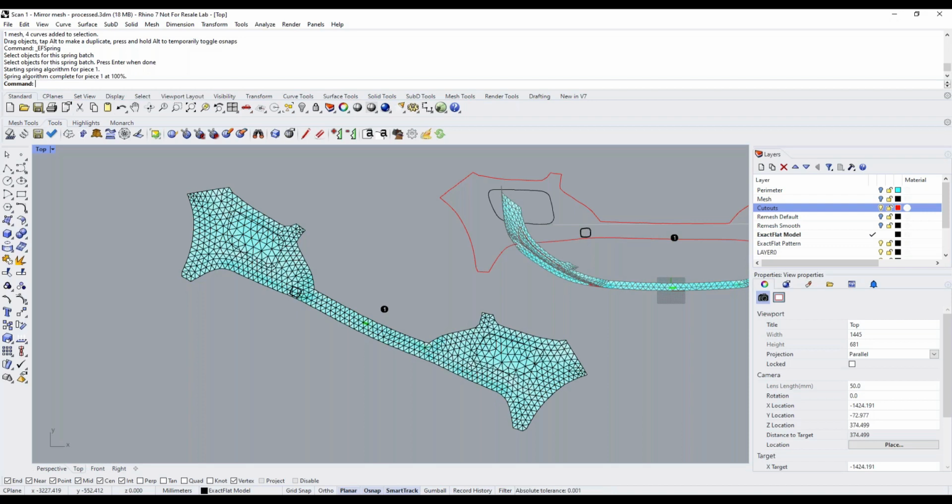And so the only nuance when you deal with metals is the plane of flattening. Is it the inside surface, the outside surface, or is it the midpoint or some other point in between? That's a consideration that you need to take into account. If it's thicker metals, that matters; if it's thin metal like sheet metal, it'll work just fine. So if you have a question about metal forming, Shane, then we're happy to talk more about that. But yes, it can be used in metal forming.